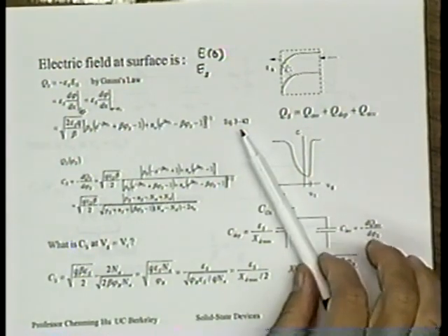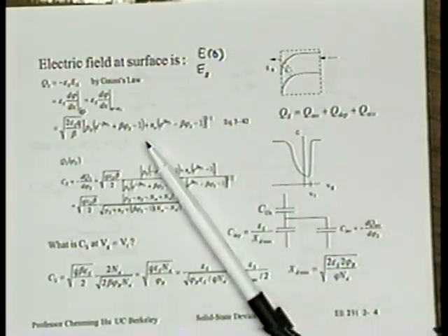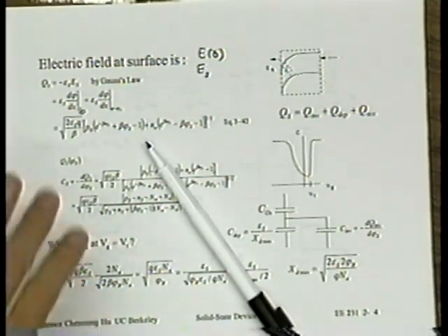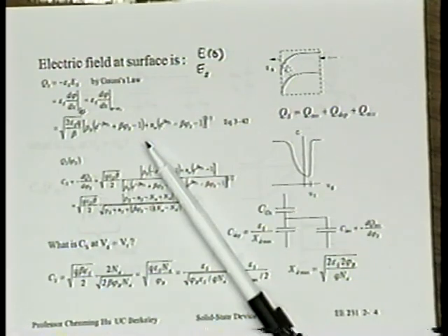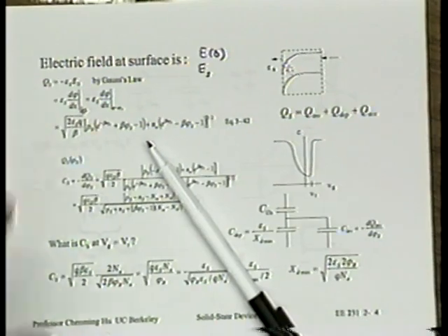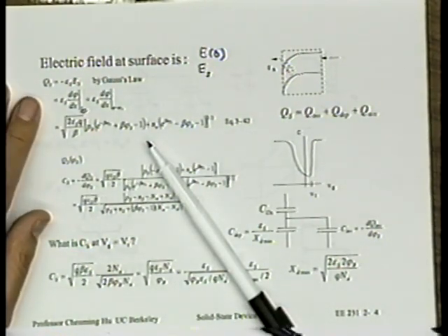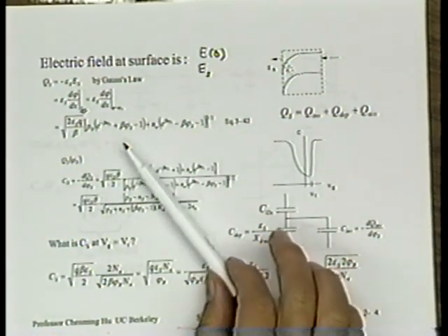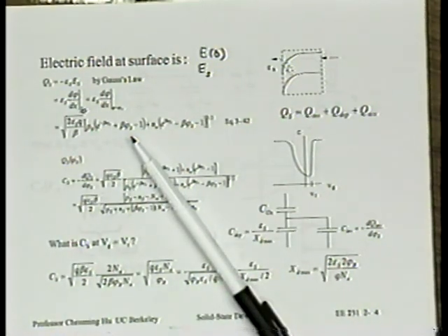All right, let's look at this equation one more time, and feel very comfortable with what we're dealing with here. What we're saying is that we now have an expression for the substrate charge density. Let's remember, I don't call this surface charge density, I call it substrate charge density, right? Because this could include the depletion layer charge, all the charge in the substrate. We know the substrate charge as a function of the surface potential, right? Complicated function, but it's an analytical function of surface potential. Is it okay?